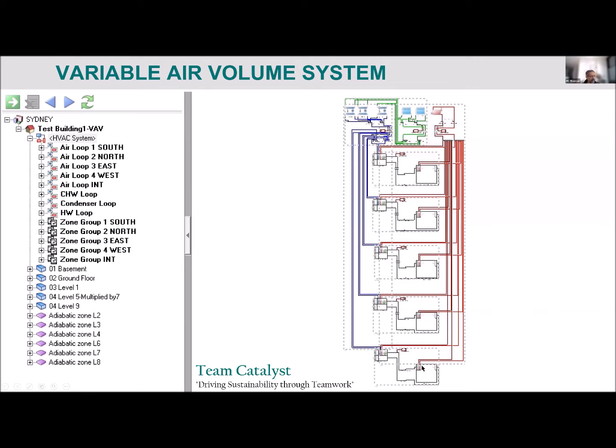So the VAV box, the variable air volume box, is here. That is supplied cold water by a set of chillers. There are 3 chillers here in this one. Those chillers are water-cooled chillers. So you've got 2 cooling towers that cool this chiller, right? And we use a boiler for heating. So it's a gas-fired boiler. There are heating coils in the AHU, air handling unit, and in the variable air volume box in this design. In other designs, it would be different, okay?